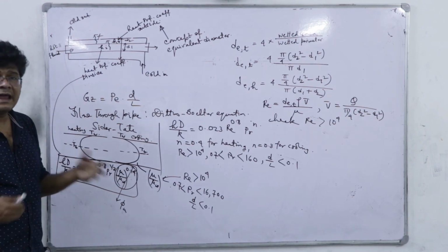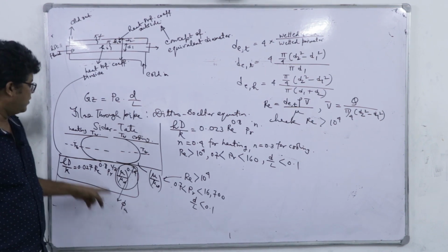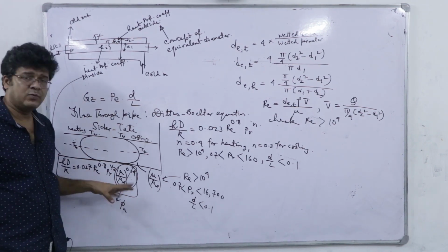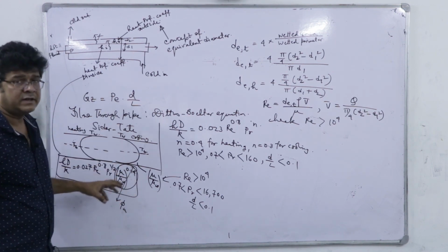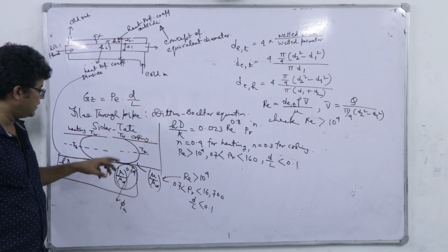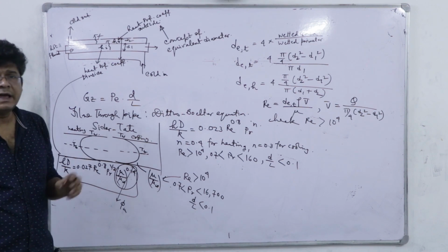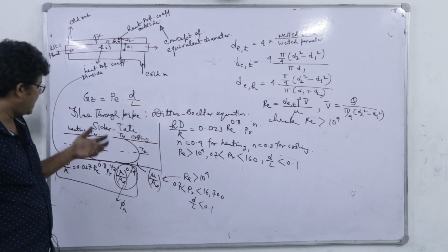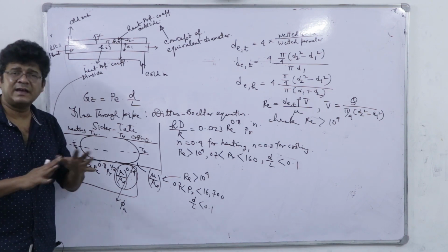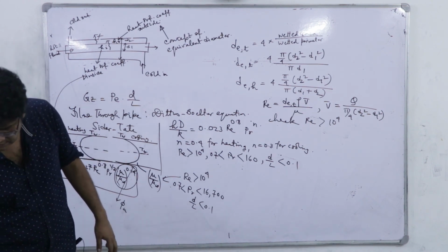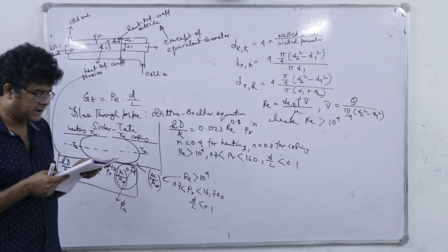Now, for standard calculations in solving problems, we do not have to consider this phi u, we can take it in most of the cases to be equal to 1. But for actual design, definitely we have to consider it, and fluid properties, they are to be evaluated at some average temperature. So, there are different customs of averaging, I am not going into the detail. That's the flow through non-circular duct.